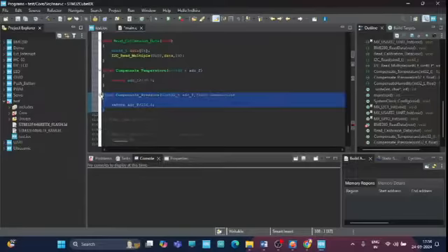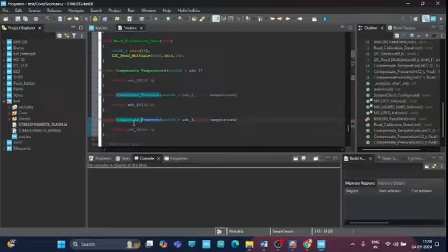And likewise, this is for humidity. So we need to change this to H, and over here 1024, and we need to change this also, right? So the raw ADC value of ADC H is divided by 1024 to get the humidity.